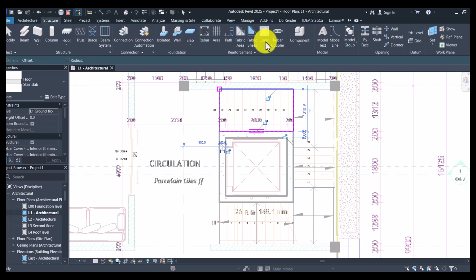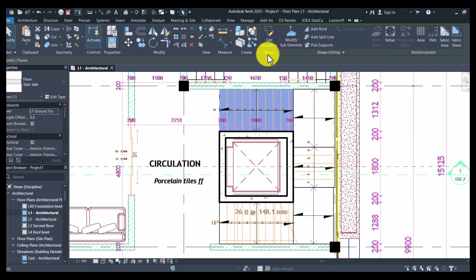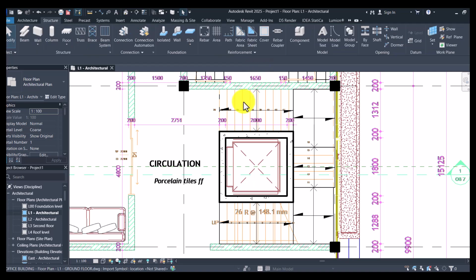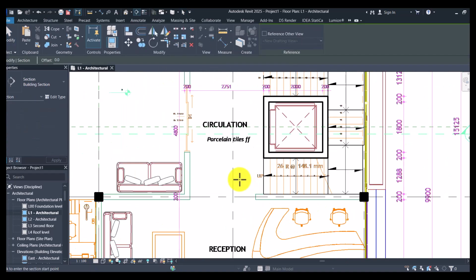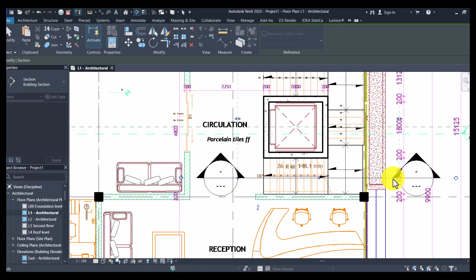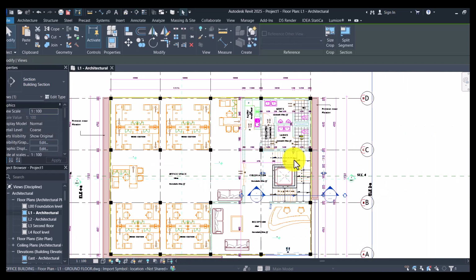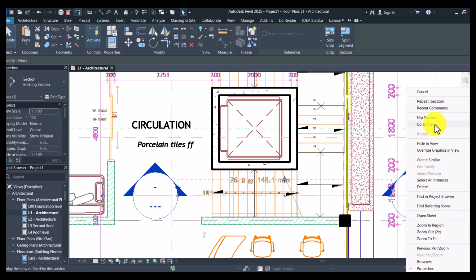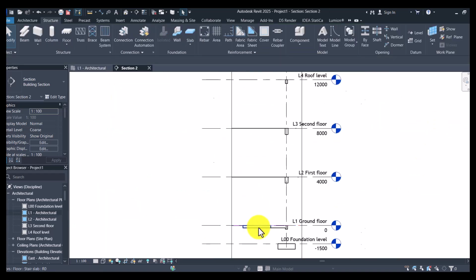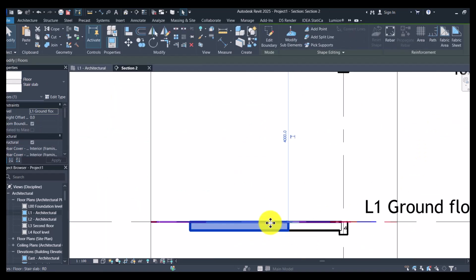Now to adjust them very well, I'm going to first cut a section here, cut a section here, cut a section there. So I'll come to section, cut one like this, drag this view extent to be around here, right click to open the section, go to view, there we go. So we have our stair currently flat, our stair slab.